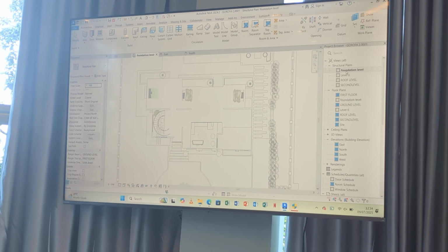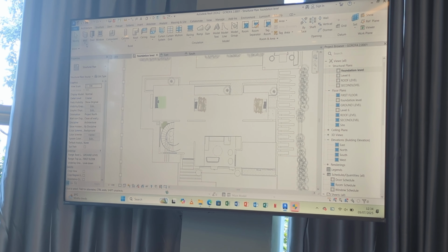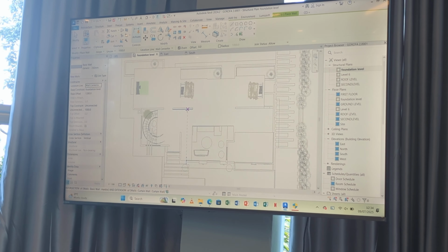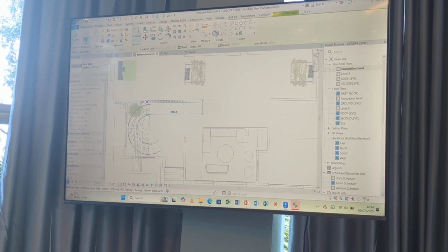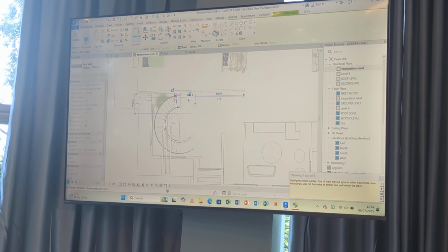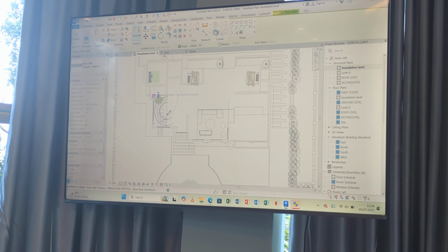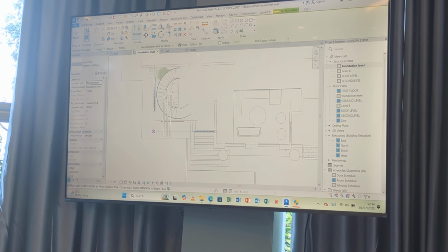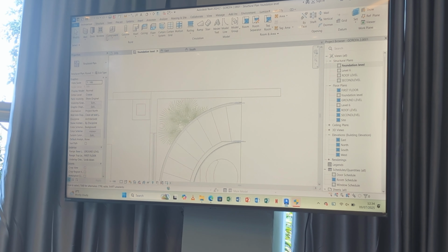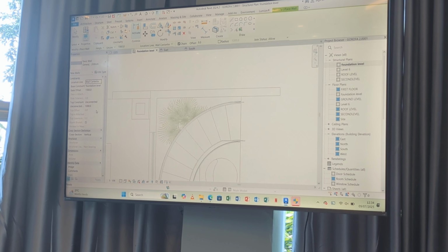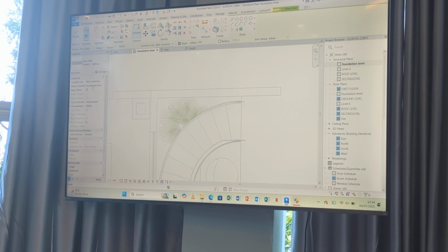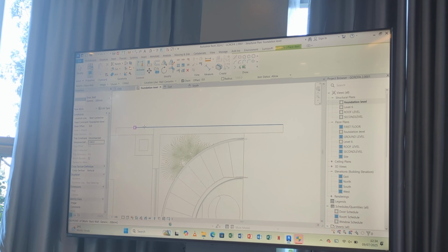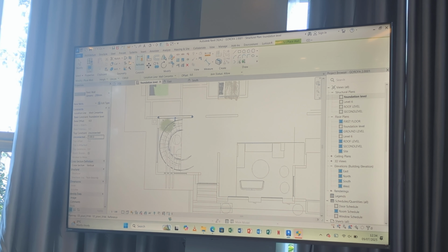Foundation under structure, confirm that it's under structure, and then for your wall, I'm using 1.3. Like I said, start drawing, keep moving around the entire structure. Why are my walls being hidden? Unconnected height. Oh yeah, I put a base offset. No, that's not a base offset. This is the base offset. It should still be on 0. It's sitting exactly on foundation, and then the height is the 1.3. You can use the thick lines tool. See that?